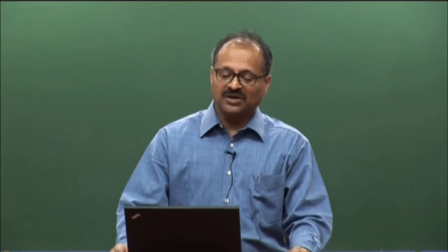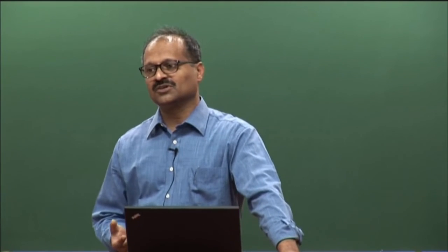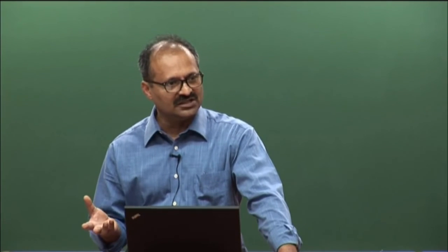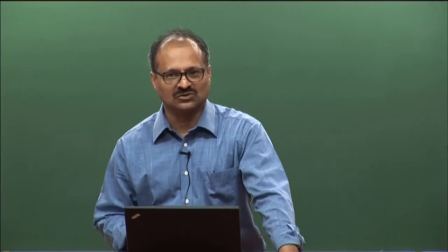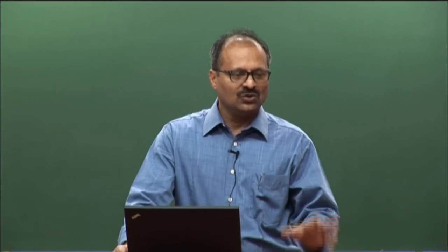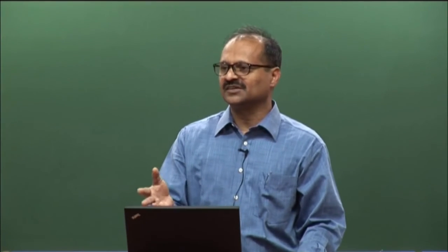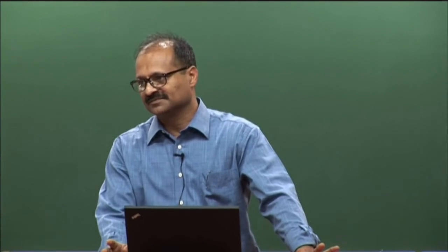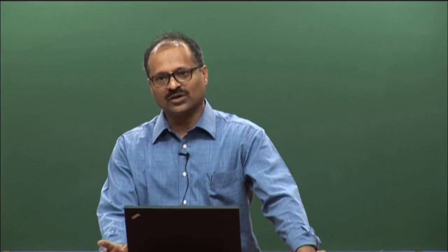right. But here it is not desirable, because you know that the second order polynomial which defines the velocity is the one which minimizes tau squared for a constant I case. Other one is too complicated to comment on right now. So, if I try to fit the acceleration, I am going into a 5th order polynomial, it is not right. It is not okay from the torque point of view.